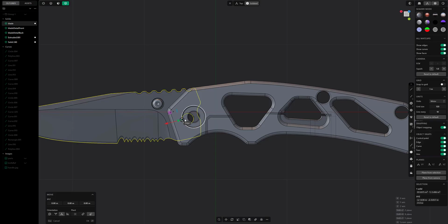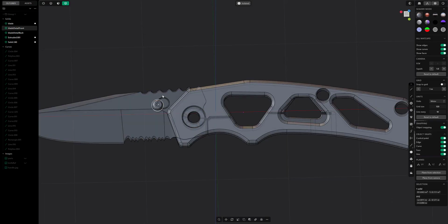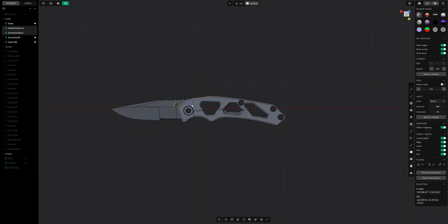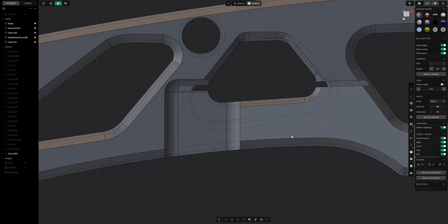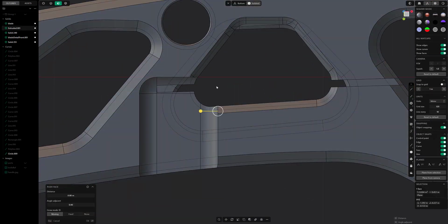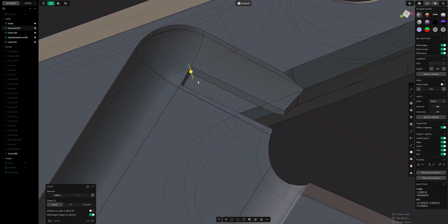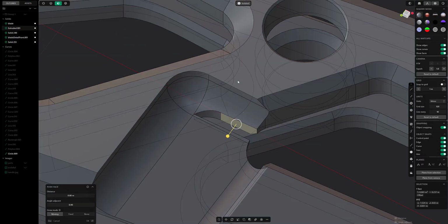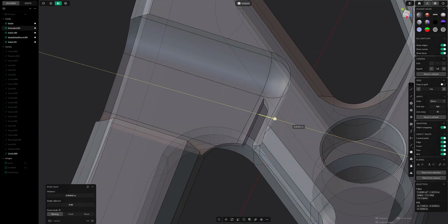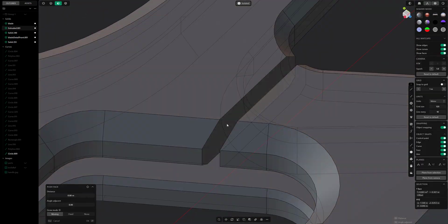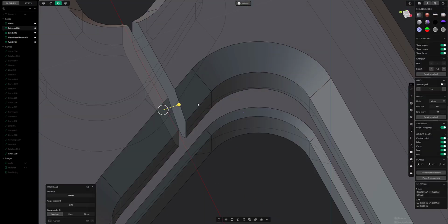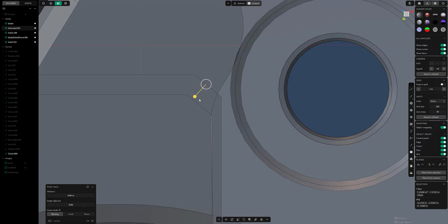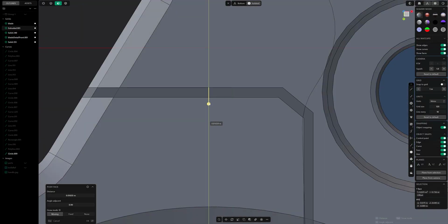Let's go ahead and move the knife pivot with V, and then Control. Remember, Control is to snap to the center, really snap to anything, and now I'm just testing, does it match up? I think I might have actually scaled the blade a little bit, and that was a little bit thick, so we moved it, and then we will chamfer that edge to match. Here I tried to pull that down thinking that that other edge would come with me. It wasn't, so I'll just go ahead and move that one up. If that was an issue, I could just grab both edges and move them both down with the Translate tool. Clearly that area doesn't impede into the pivot, so let's just go ahead and move it.